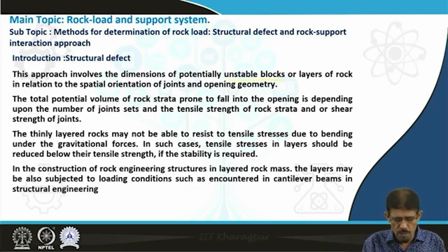It considers the total potential volume of rock strata prone to fail into the excavated opening, depending on the number of joint sets, the tensile strength of rocks, and the shear strength of joints.